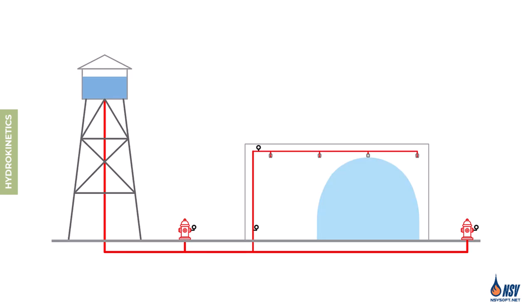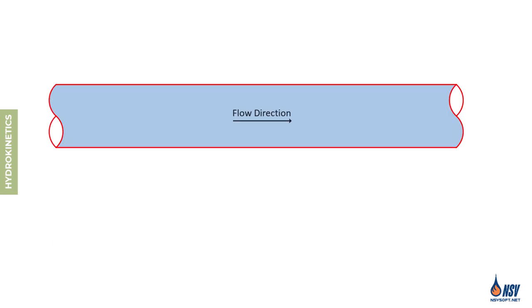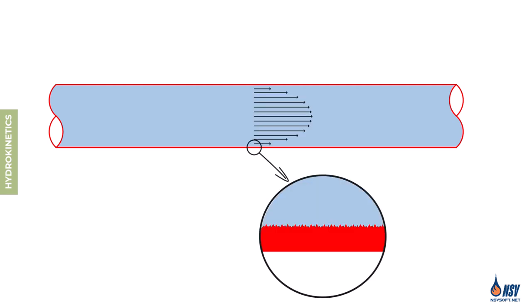When a sprinkler activates, water begins to move through the piping network. In this flowing condition, pressure is affected not only by elevation changes, but also by other factors related to how water behaves inside the system. As water travels through the pipes, some pressure is lost due to friction between the water and the internal surface roughness of the pipe.